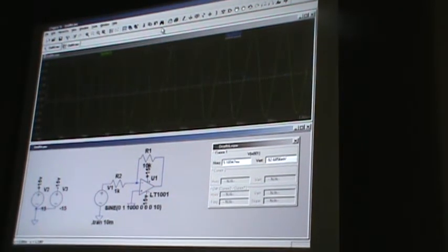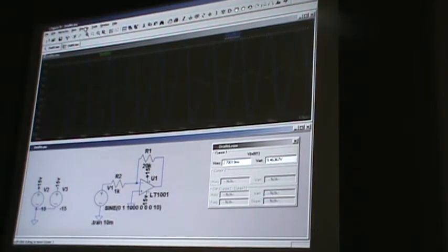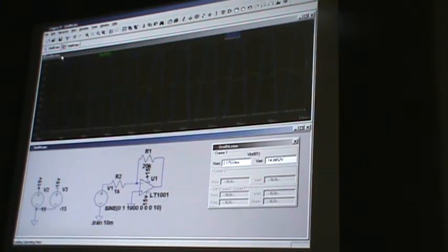You can simulate your sensor. If you want to have the minimum pulse width of what you want to read, and you want to amplify that with your own transistors, put your transistors in there. And obviously you want to buy the transistor of the model you're using, because they do try to get the exact characteristics in this model, so you get a real life representation of what your transistor circuits are going to do.